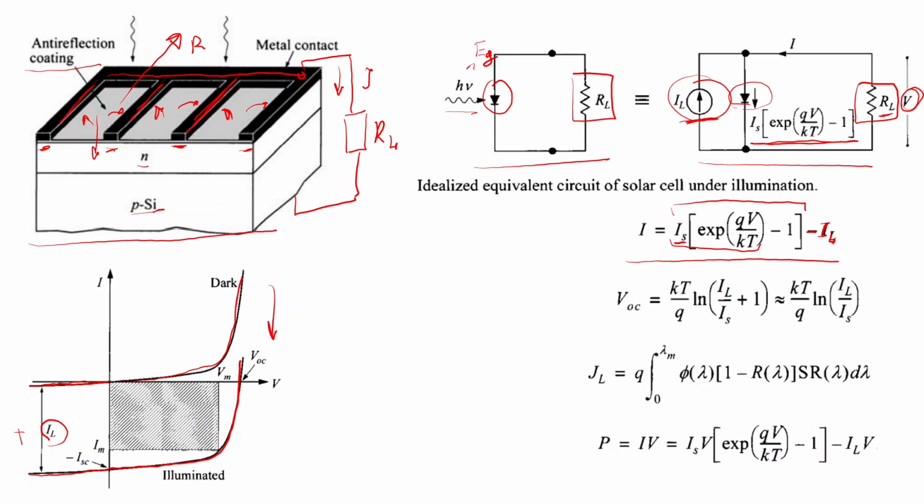So we have actually negative current, large negative reverse current flowing through the illuminated solar cell, because that is equilibrium reverse current in the dark, very small, plus very large reverse current, which we call photocurrent now. So it is shifted downwards, and we have such a so-called fourth quadrant of this current-voltage characteristic, which we need to consider. So take this away.